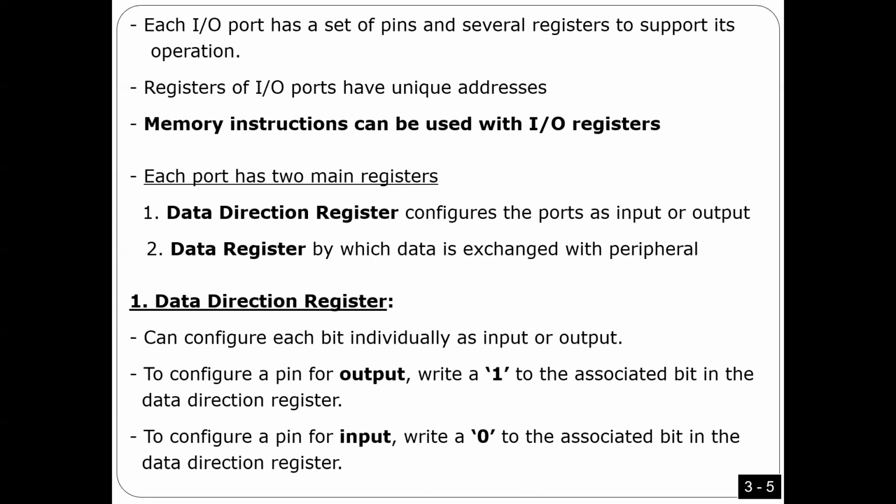For example, if an LED is connected here, that means when I put here 1, I'm going to make here 5 volt, I'm going to turn it on. This is how we can turn an LED on, right? But if this is an input, actually all you have to do is you have a byte and you need to check some bits. And we have been doing this many times. We did it many times, right? So I have to check some bits. Okay, guys?